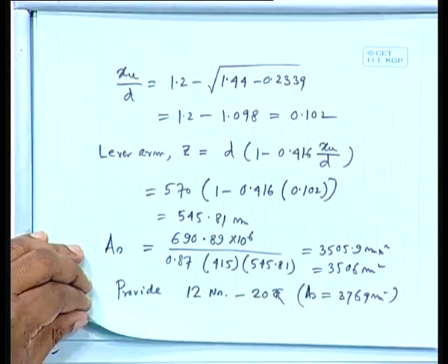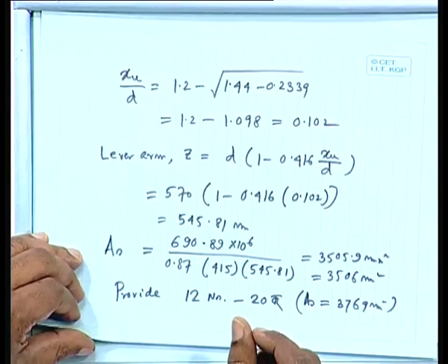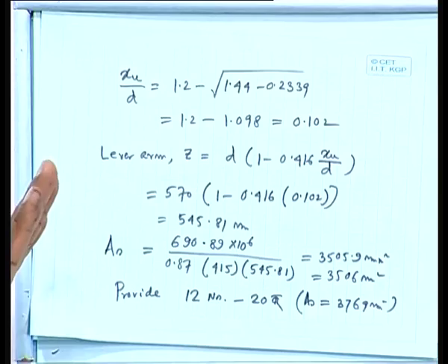But in beam, we are taking the full width, we know the definite length, and that is why we are providing the numbers. So where you know the full length, you specify the exact numbers. But where you are only calculating on the basis of a unit area or unit length, then you specify a spacing. Okay.